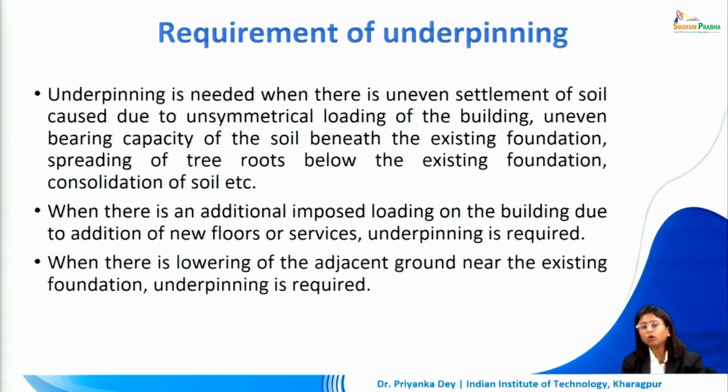Maybe there is spreading of tree roots, a very common phenomenon below the existing foundation that can definitely cause harm to the foundation and the stability of the overall building. There might also be some problem with the consolidation of the soil. Soil undergoes changes in its properties, in its chemical composition, in the way it settles over time, that might require me to undergo some changes in my foundation.